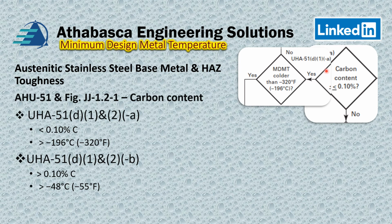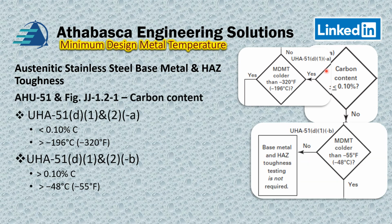And if we continue, we'll look at the bottom part here. In this case, we've got a carbon content greater than 0.1. So then we look at the MDMT again. This is colder than minus 55. So that means, if we meet this criteria, we don't have to impact test them. But if we go to yes, then we do have impact testing.